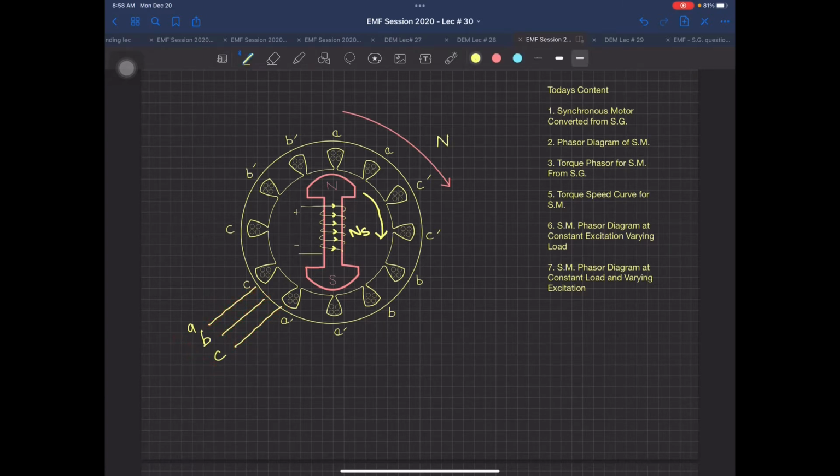In synchronous motor, you are going to give A, B, C three phases, which is going to produce a magnetic field with speed ns, of course, and that is going to be given as 120 F by P. And now in this machine, you are also going to give a DC supply over here at your rotor, and this time you are going to use slip rings also because you are going to provide DC. You can't use any brushless exciter or pilot exciter scheme because here the motion is going to be created by you. Otherwise, in the generator part, the motion was already inherently available because of the turbine used over there.